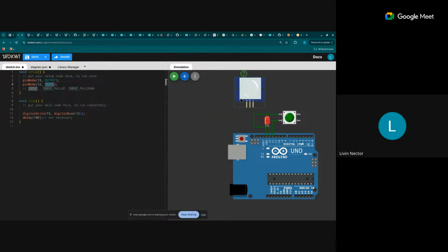When you connect this device, you will be connecting a voltage and a ground, and this pin will have an active voltage coming out. During that time, you will set the mode to input instead of input pull up. When you have a passive input device which doesn't have a voltage source, it works by shorting the value. You want to note that.